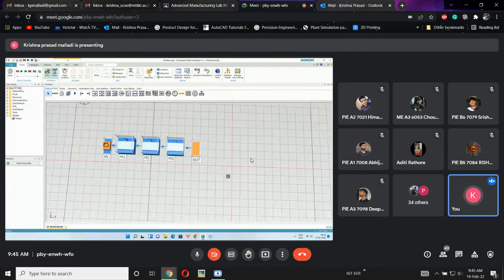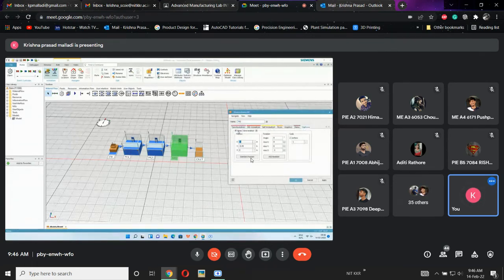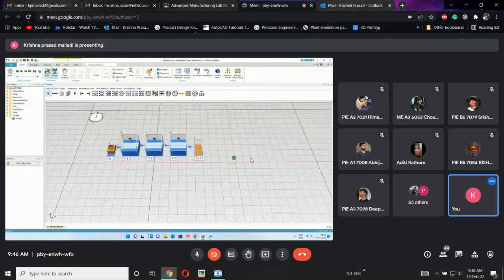So this is how I want to showcase it in 3D, whereas in 2D, everything will be automatically visible. But in 3D, if you want, you can make it visible. You enable it. If you don't want it, you can rename it, or you can hide this name. To hide it, same: edit 3D properties and go to captions. Just disable this one, so it will be hidden.